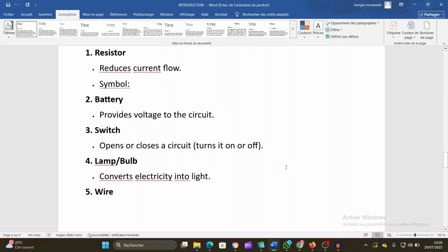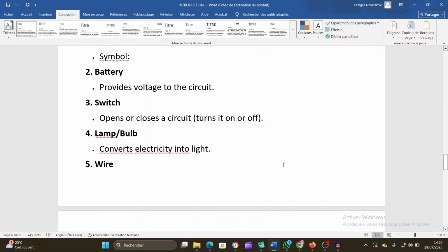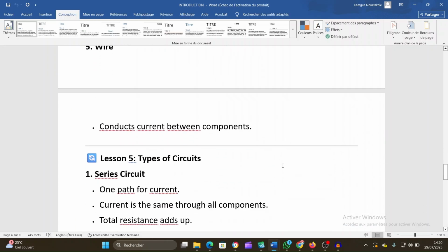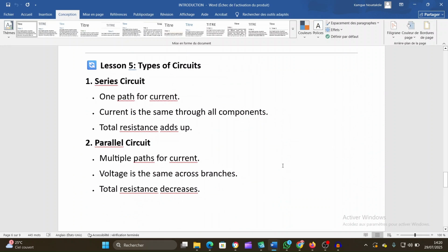We mentioned safety measures. We don't need to touch live wires. If it becomes necessary or urgent, we need to be trained and then use insulated tools.